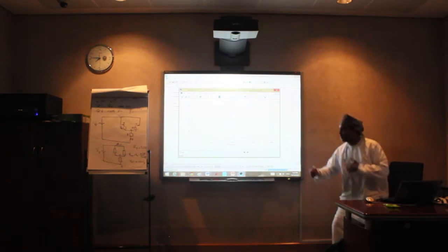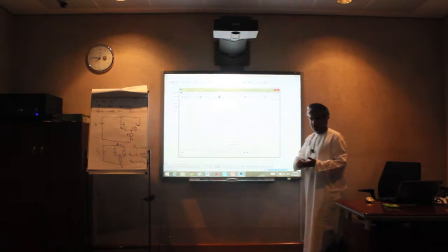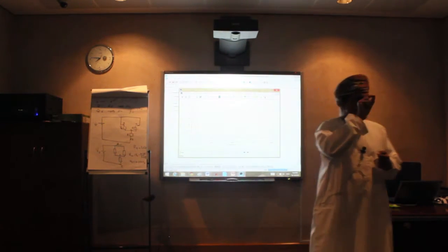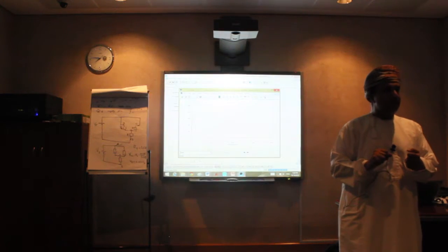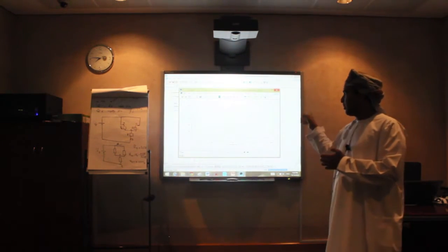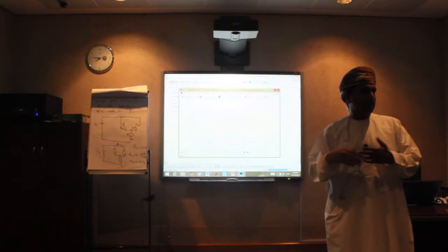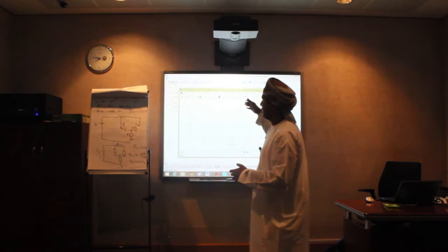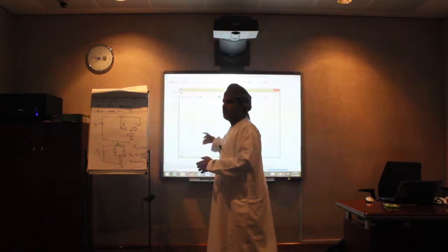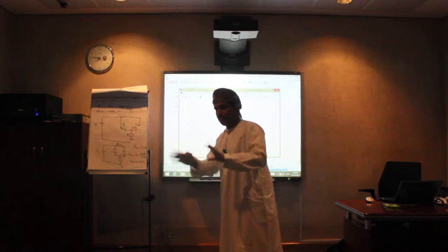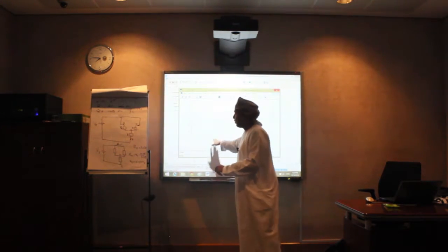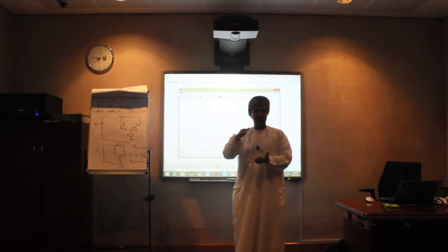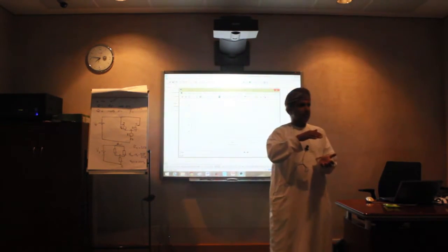And the beauty of this one as well, you can control the value of the voltage by changing the pulse width, the modulation index. Okay, and you can change the frequency. So it has a good opportunity to use it to change the voltage, the frequency, the phase shift, whatever you like, for the drive. And also if you would like to connect this one to the grid, it's easier to design a smaller filter compared to the 6 pulse.